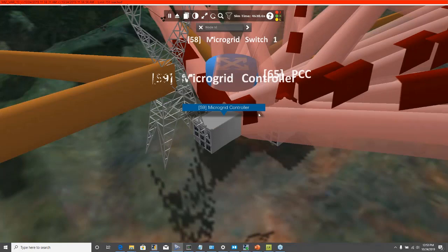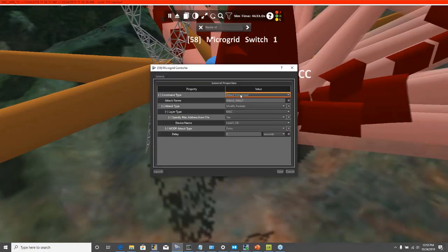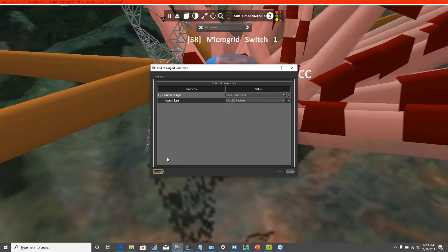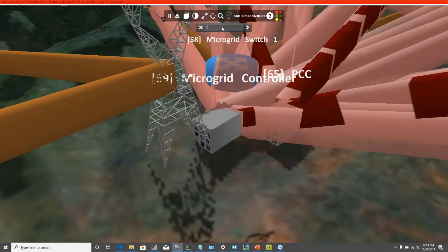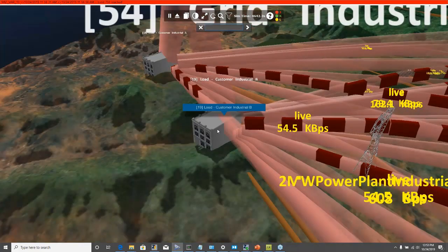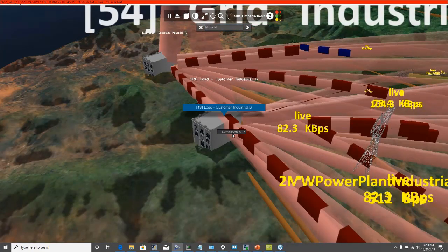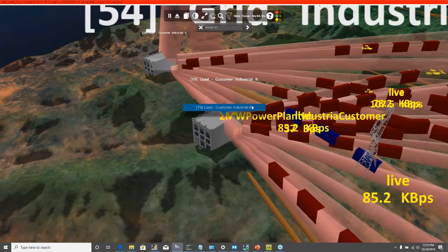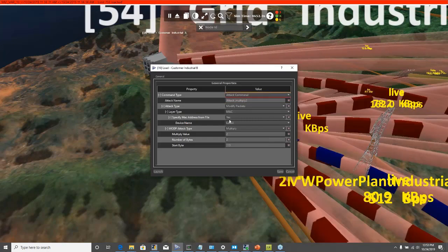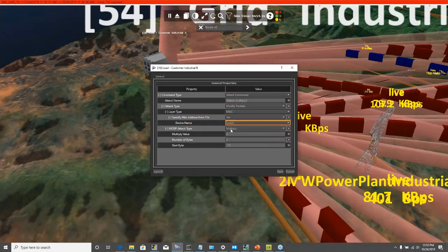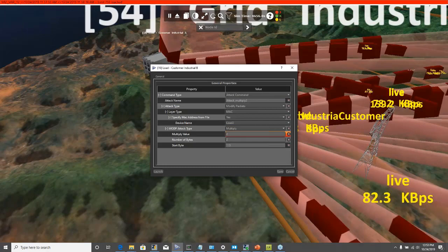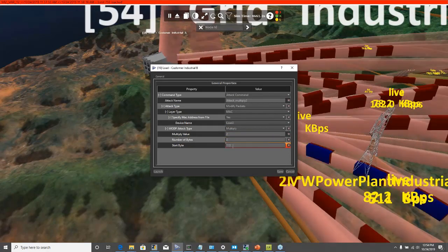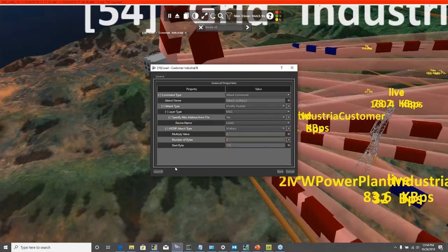We'll go to the delay, stop the modified packet attack, and we're going to go to load 19, which is our load. And we're going to apply the multiply attack. Same principle here. So we select the load 2, multiply by 2. In this case here, we attack specific bytes in the GOOSE message. We start at byte number 113. For 2 bytes, we multiply the value by 2.